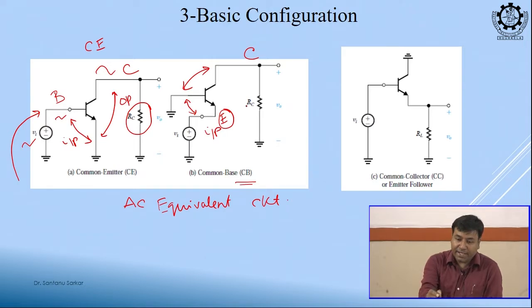Now, see, in this case can you guess that it should be opposite phase or in phase? See, now base emitter voltage is base voltage minus of Vi, one minus sign already came, this minus sign will cancel. So, it will be in phase. Are you getting? If Vi is increasing, this V0 supposed to decrease, but this is already in the emitter side.